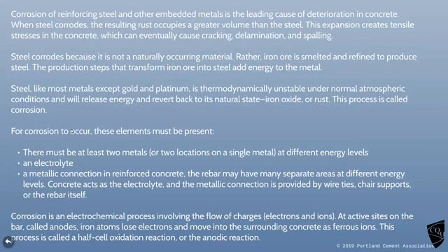Corrosion is the main thing that gets reinforced concrete, so you always want to stop the reinforcement corroding. When steel corrodes, the rust expands, and when it expands, it pushes off the concrete around it. And of course, once it's expanding and pushes the concrete off a bit, there's no longer a real bond between the reinforcement and the concrete, so you're rapidly losing strength in that reinforced concrete member, and then bits of it are going to fall off and delaminate.